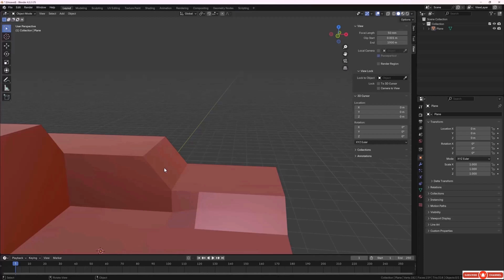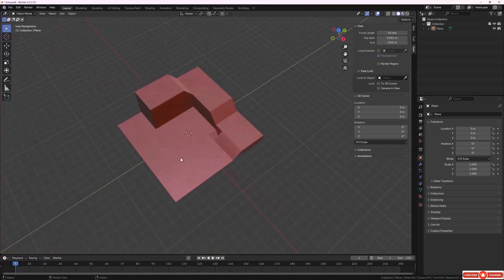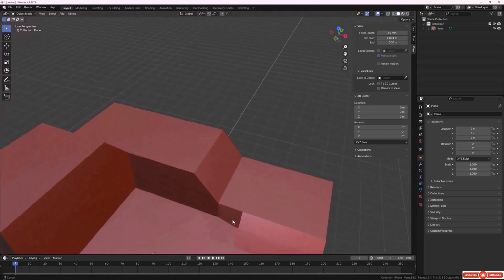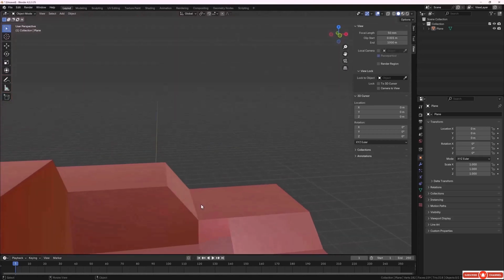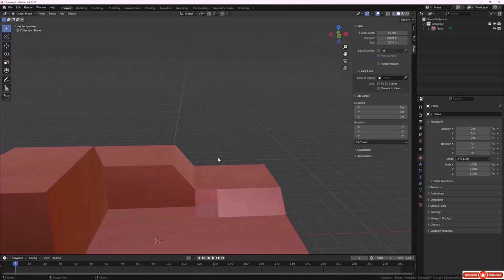We're going to do a house with 2 stories and different rooms, and it can be quite difficult to move around it. So we can actually walk around the house quite nicely. We can use the walk fly mode to do that. So what I'm going to do is actually just make sure that I'm directly over this little model as I'm doing this. So what I'm going to do is press the Shift tilde key. And if you don't know which the tilde key is, it's the one directly above your Tab key.